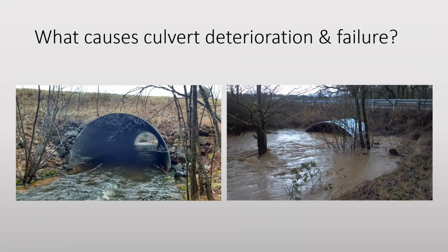Now, additionally, rainfall, flooding patterns, and other storm events can expedite culvert failure if the water is unable to flow through the structure under the design parameters. This is due to the increased hydraulic pressure that builds on the upstream end of the pipe. These factors will lead to an increased likelihood that the culvert will fail if the structure is not inspected and documented accurately and regularly.